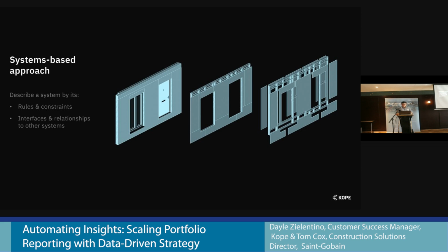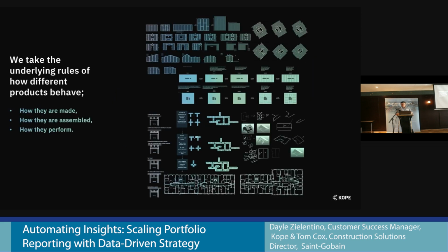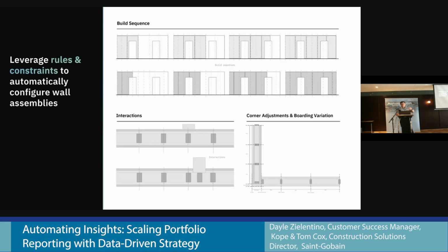We go right down to the studs and the screws and the fixings to understand spatial arrangement. You can't have two studs that are too close together. It's just non-buildable, and we end up with a coordination issue on site. We understand how MEP works. If you bring in a pre-manufactured panel, you really need to understand what you're doing with your MEP and services to make sure that you're not having to do abortive and redo work on site. There are all of these pieces that come into the platform.